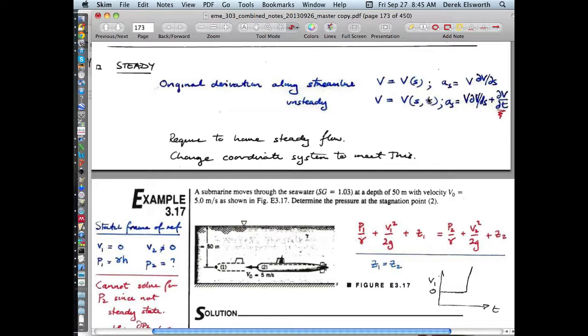What I will do is add to this lecture a little derivation to show that you could, if you wanted to, take a tank which has a free jet coming out of it. And we know that that free jet would be coming out at some velocity v2. And we've always assumed that the velocity on the surface, v1, is equal to 0. But we don't necessarily need to do that. So what we could do is apply Bernoulli to take this velocity, v2, as basically equal to the square root of 2gh, where this is the height here.